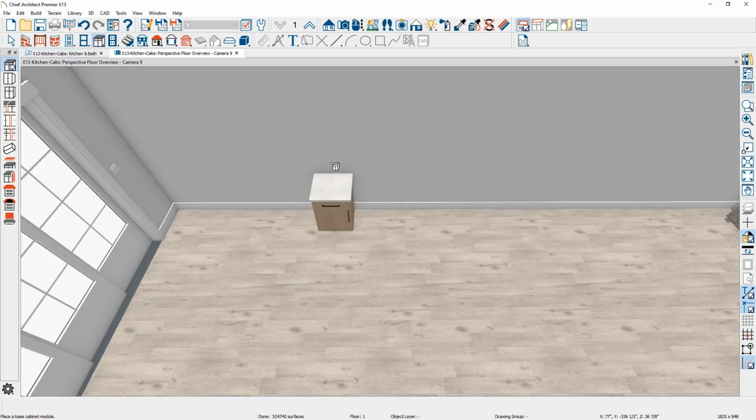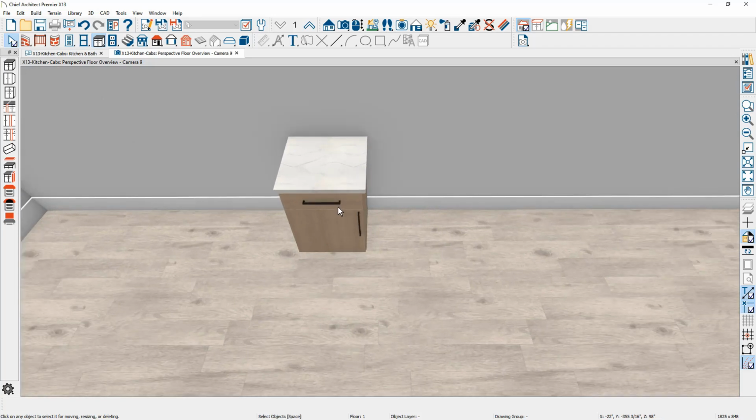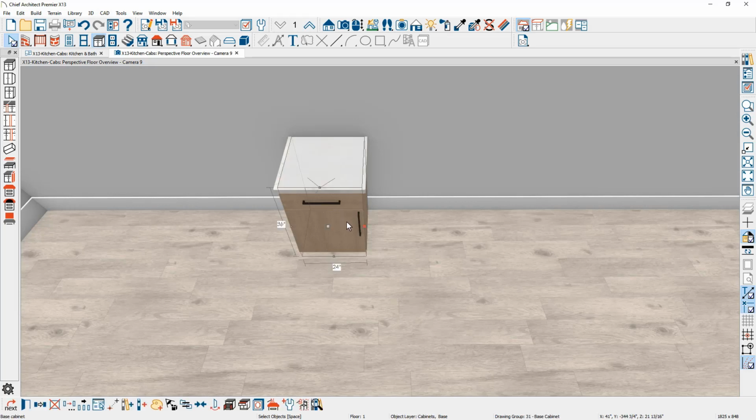When you place a cabinet in the program, the cabinet defaults are such that you can define what the countertop, what the door style, and what the hardware looks like. Then when you click on a cabinet and resize it, our cabinets are set to bump in 3-inch increments. Also notice that when the cabinet is 26 inches and wider, there is a setting that will change the door to a double door. You can always override that.